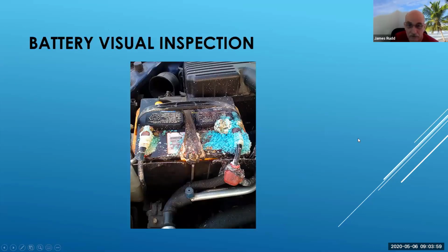And then this is not over illustrated. You're going to find cars that sometimes come into your shop, and this is what they look like. Now, I'm going to give you the heads up on this. When it's this bad, that battery is pretty much toast. You're going to find it's probably sulfating pretty well. And also, my concern is the battery cables. If it's up here, this fuzzy and green and stuff like that, believe it or not, it's actually going all the way down the cable. So those cables really need to be replaced.